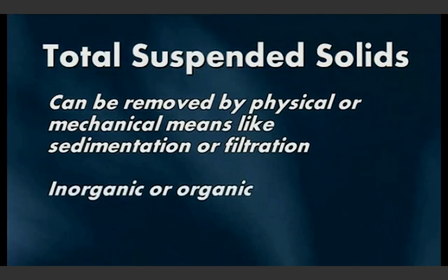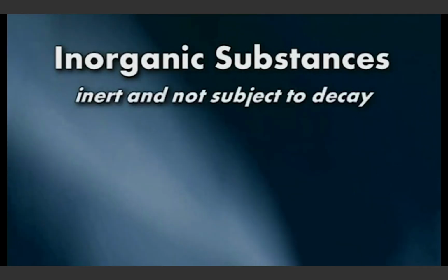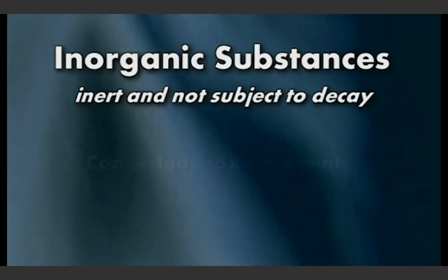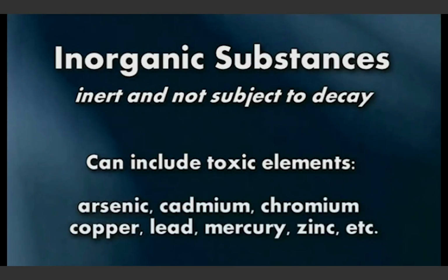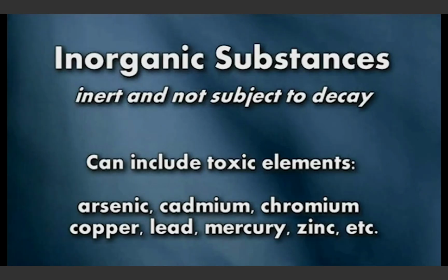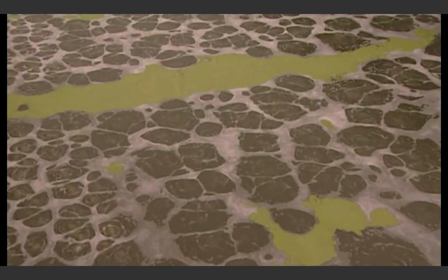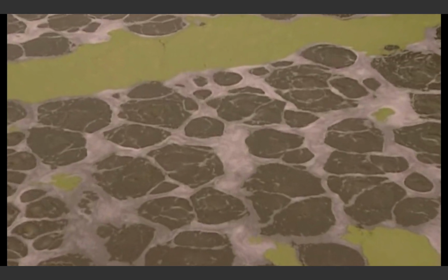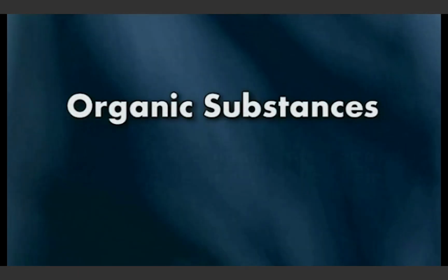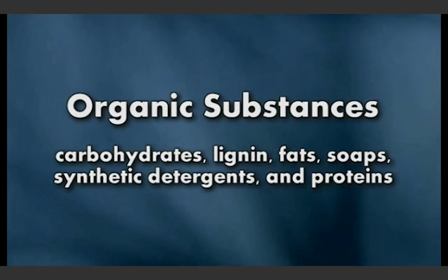TSS are further classified as inorganic and organic. Inorganic substances are inert and not subject to decay. They can include a number of potentially toxic elements such as arsenic, cadmium, chromium, copper, lead, mercury, zinc, etc. Typical domestic wastewater is composed of about 50% organic material which will decay or decompose through bacterial activity. Among the organic substances present are carbohydrates, lignin, fats, soaps, synthetic detergents, and proteins.